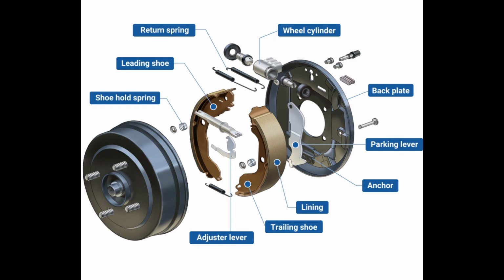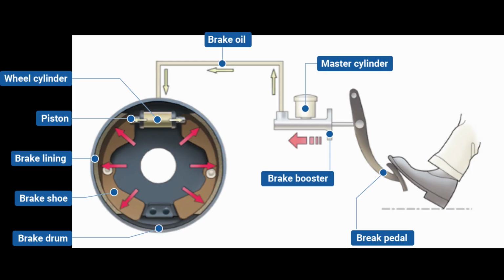4. Drum braking system. A drum brake is referred to as a brake system in which friction is caused due to the impact of a set of brake shoes which is pressed against the inner surface of a rotating drum. The drum is directly connected to the rotating road wheel hub so that it can work efficiently. A rotating drum with a pair of shoes which expands to rub inside the drum is commonly known as a drum brake. A drum brake refers to that traditional brake wherein the friction is caused by a set of shoes or pads which is pressed against the rotating drum, which is a shaped part known as a brake drum.